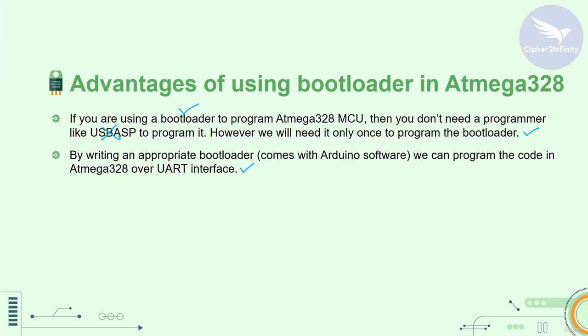You already know that we can use multiple interfaces like UART, SPI, I2C. But the bootloader code provided by the Arduino organization is capable of programming the microcontroller over the UART interface. That's why I have written UART interface here. Now, from this point, you might not yet have clarity about the advantage of using a bootloader in the Atmega328, but from the next point you will.